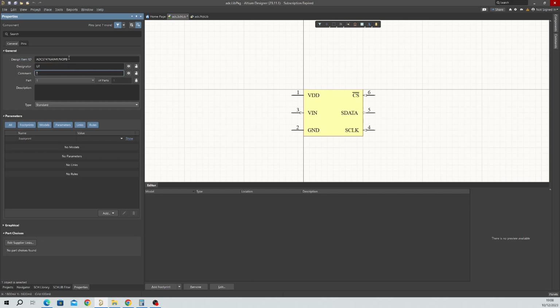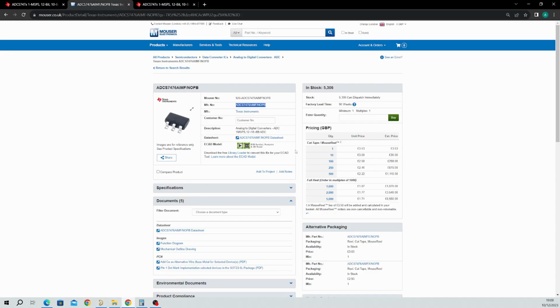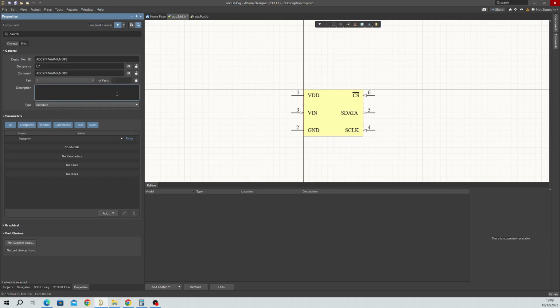Now for the comment, on the previous video, we put in like 1K 0603 blah blah blah. Now an ADC part number is pretty unique, so I tend to just go with the ADC part number, to be honest. The description, well, we get that for free, so we can just put that in there. And this version is a 12-bit ADC, so we can just put that there, and that's it. So that's all this top part done.